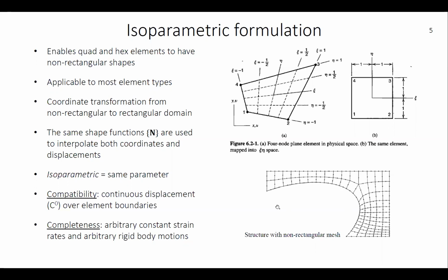So the displacement field is continuous, but if you have C0 continuity, we may have a discontinuous strain field. So the strain or stresses may have gaps in between the elements, or not gaps, but rather discontinuities. This is often quite unrealistic because we would expect the stress field also to be continuous. But if you evaluate the stresses within adjacent elements, you find this gap.